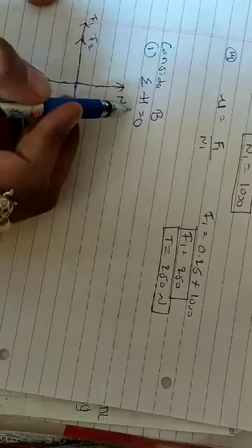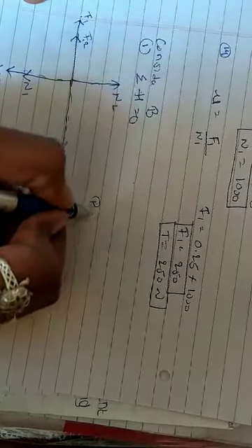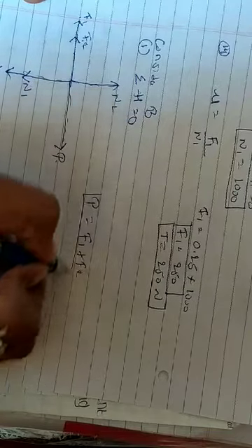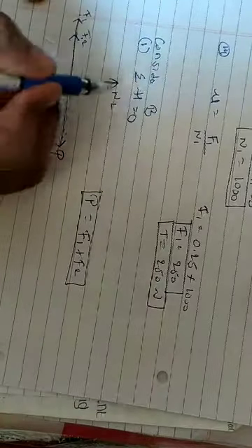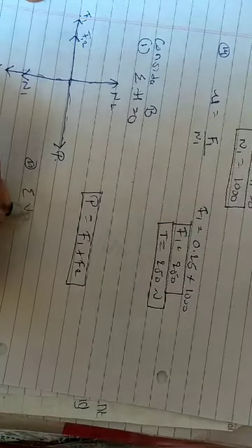Now we can write this equation. First, summation H equal to 0, that is plus P minus F1 minus F2 is equal to 0. So we can write P is equal to F1 plus F2. This is from summation of horizontal forces is equal to 0. Second condition, summation of vertical forces is equal to 0. So plus N2 minus N1 minus WB is equal to 0. So N2 is equal to N1 plus WB.